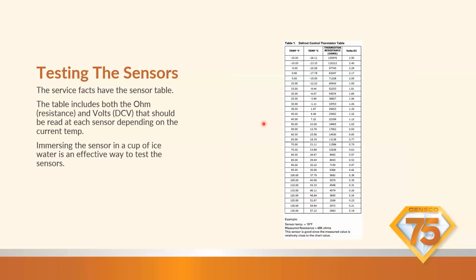It's easy to read. You'll notice here that these ohm readings are kind of high. So at like 75 degrees, we're at 10,000 ohms. So make sure your meter is set to do kilo ohms, 1,000 ohms. And make sure that when you're reading it, you look for a little K symbol usually in the corner of your meter. Otherwise you might say, oh, only 10 ohms, that's really hot out. No, it's 10K usually.